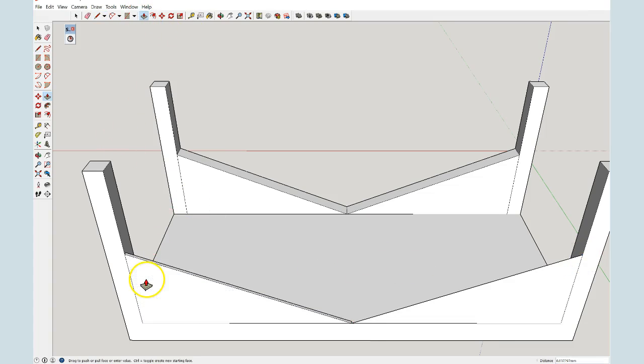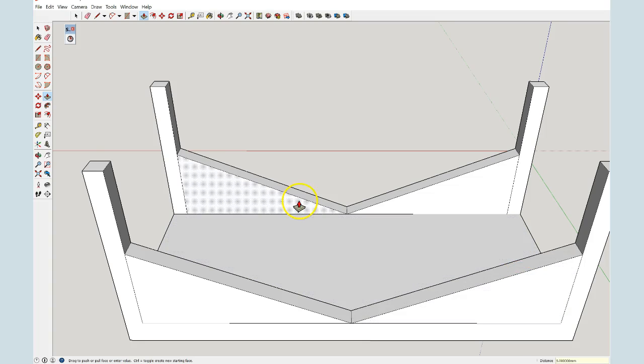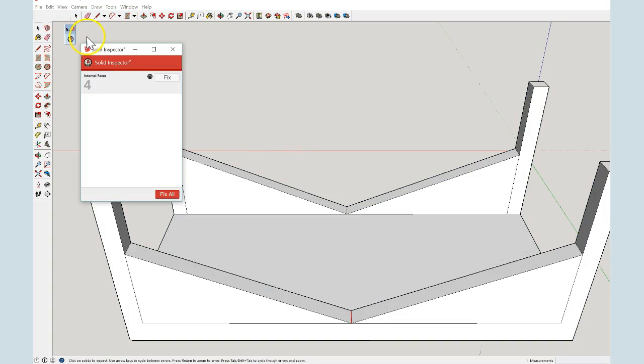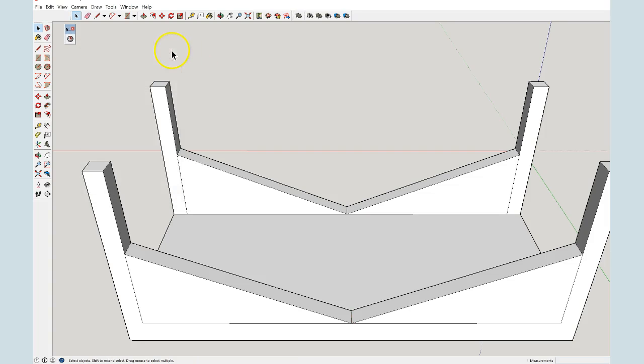And so now this time, since I'm looking at it from the opposite side, I'm just going to type in the dimensions. I know it's 5 millimeters thick, so I'll just type in 5 millimeters for each. Okay, so now again, I'll get my select tool, triple click everything, and run my tool. And again, I can fix that, and it gives me a ready to print object.